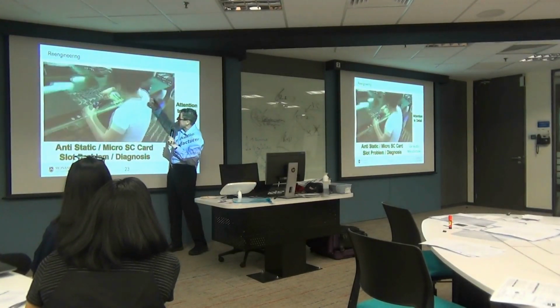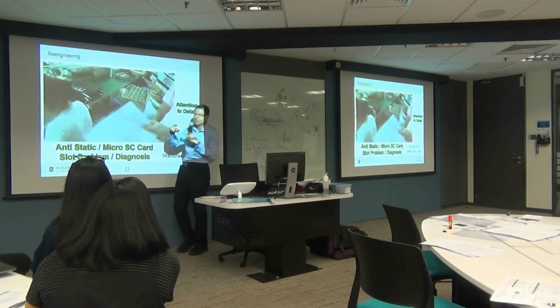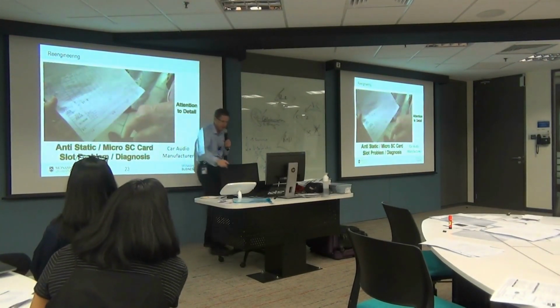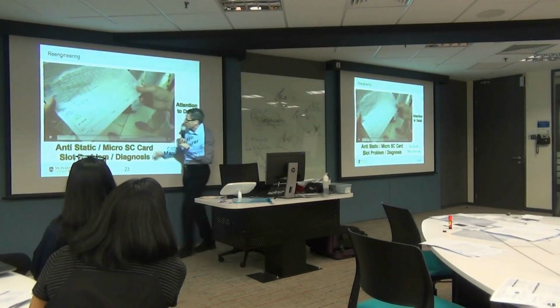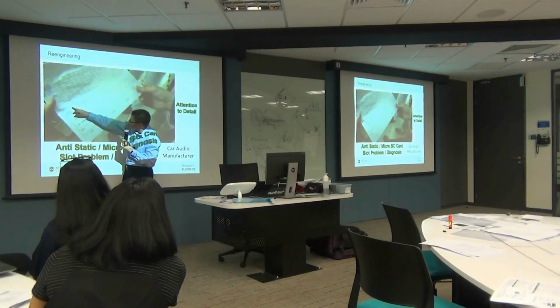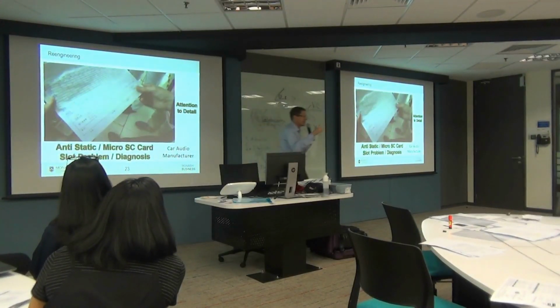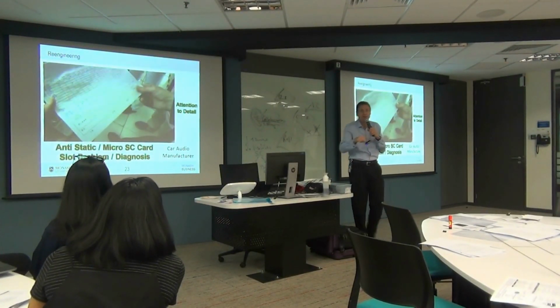There's USB going there, but an SD card goes in there, but the SD card doesn't fit in there properly. Pay attention, please. Right, see there's the QC chart. We look at the QC chart and there's a problem. What is the problem? Well, there's a major problem here where a lot of the units that get to that stage, the SD card is not going in, it's not reading properly. In other words, it's not lining up.